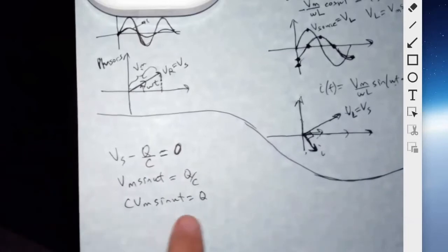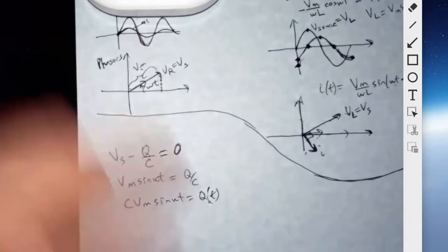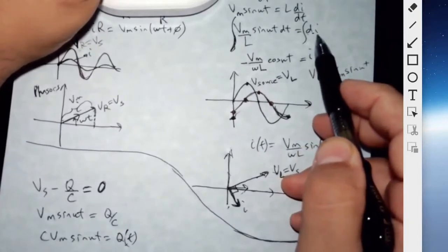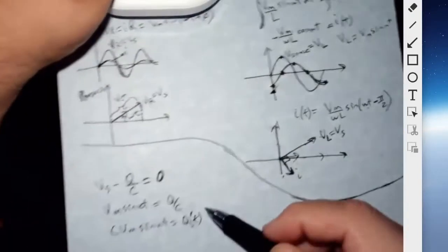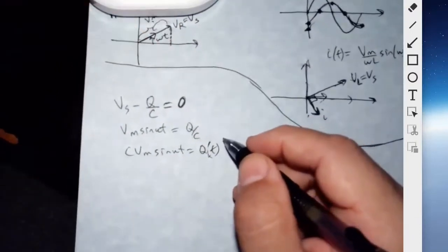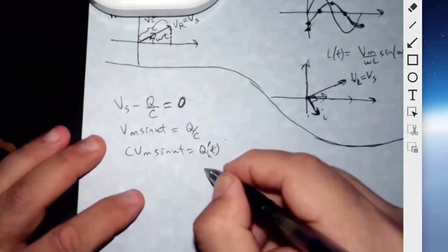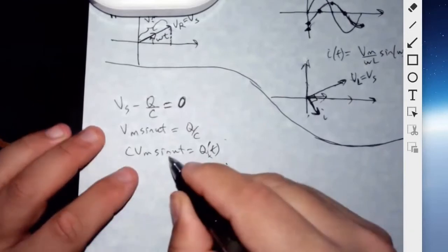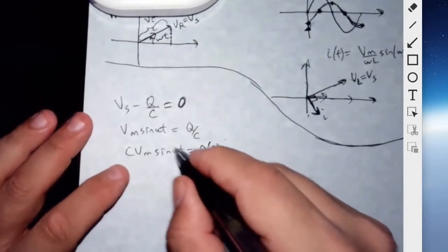So in other words, for the capacitor, we're given the charge on the capacitor as a function of time. Now, if I want to know the current as a function of time, I take its derivative. You see, it's opposite. Here, I know the di dt and then I integrate it, whereas there, I know the q and I differentiate it. So now the current is going to be dq dt, and the derivative of sine is cosine, and then the omega will come out.